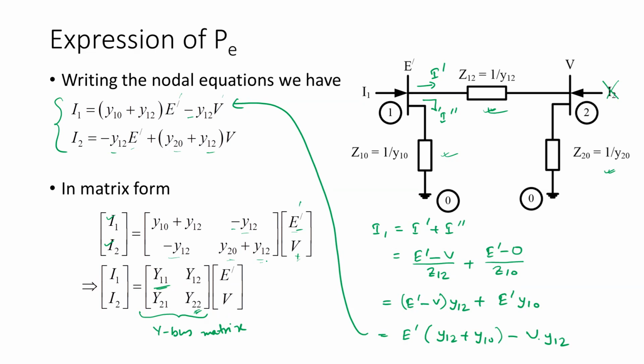Sir, according to the admittance position between two buses. Again, repeat. Sir, for Y12, we will take the negative of the admittance between bus 1 and bus 2. So for Y12, you take the negative of the admittance connected between node 1 and node 2. So finally, if you form your matrix, the Y bus matrix becomes what? A symmetric matrix or asymmetric matrix? Symmetric matrix. Very good. So this is your Y bus matrix, which is fine.